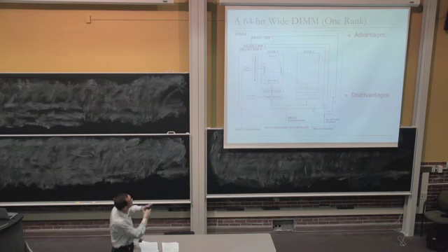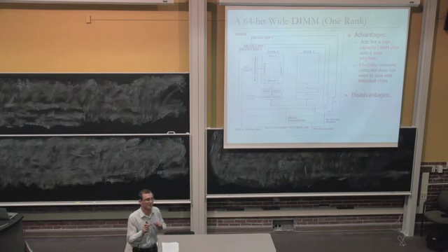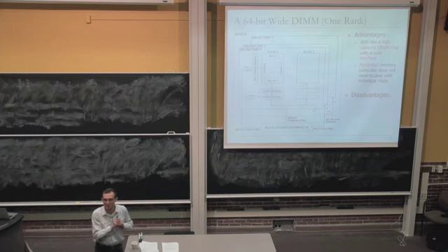Okay, so advantages of a wide interface. Basically, you have a wide interface, right? You don't need to read 8 bits at a time, right? You also gain capacity, right? So basically, this is how you build a higher capacity system that has a wide interface. And it gives some flexibility, or ease of design, to the memory controller, because the memory controller doesn't need to deal with individual chips, right? Individual 8 bits.